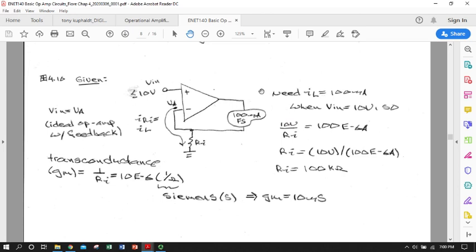And some of those types of instruments are very, very accurate and are used for standardization today. So not to be dismissed. In any case, this thing really needs 100 microamps for a full scale. So we need to design an op-amp circuit that will allow us to have that much. And we need that 100 microamps to correspond to a 10 volt input voltage. So what value of inverting terminal resistor would we use to achieve that if we needed to?